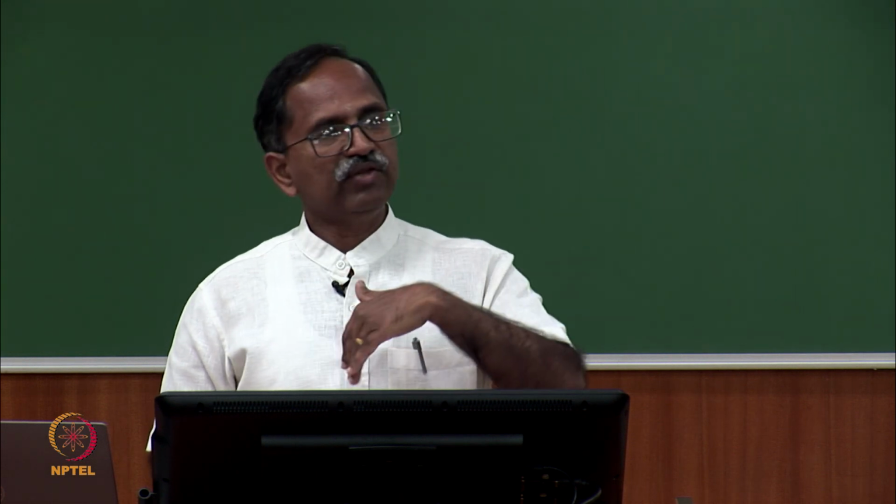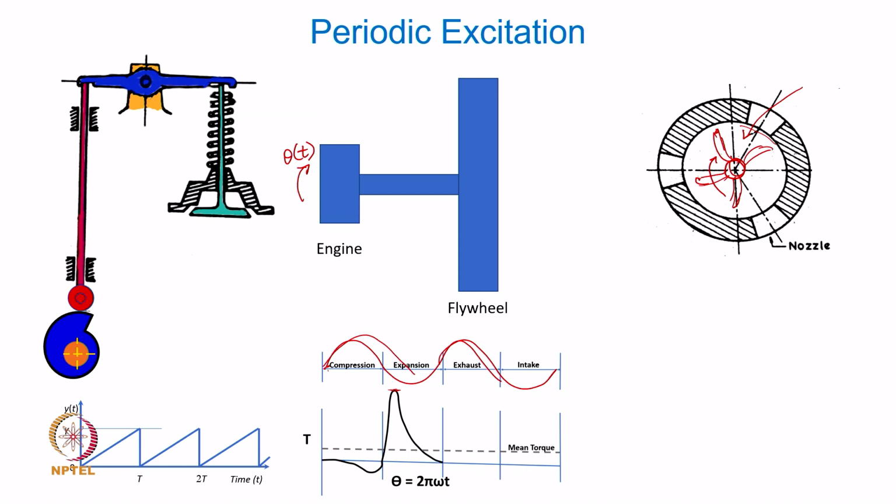So, once in one rotation, if you focus only on one blade, because one blade itself is a vibratory system, it is a cantilever, isn't it? A blade is nothing but a cantilever in action. Now, think about that blade making one rotation. In one rotation, each blade is going to be subjected to how many such pressure perturbations or force impacts?